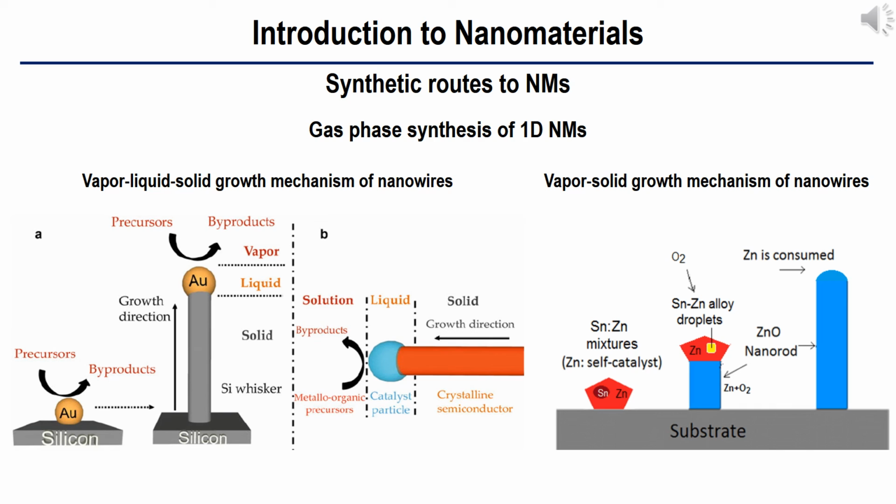The thermodynamic instability can be relaxed by the extraction of the supersaturated silicon molecules in liquid phase, and the extracted liquid phase undergoes a phase transition from liquid to solid since the surface temperature of the gold is lower than the melting point of silicon. The continuous supply of the vapor phase silicon precursor molecules into the gold nanoparticles leads to the directional growth of extracted solidified silicon, which turns into the long nanowires or nanorods.